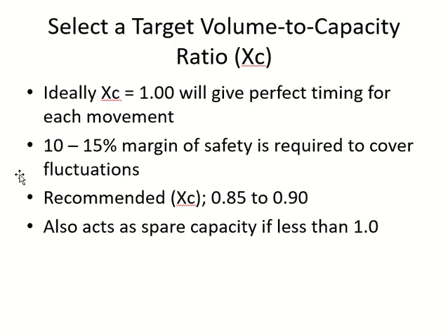Saturation is at minimum headway. Speed doesn't matter, because we are measuring from the interval. So saturation flow rate does not consider the stopping. Capacity is the actual capacity, with the red and the lost time and everything.